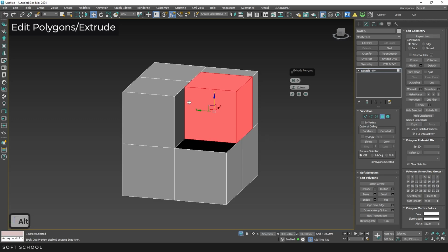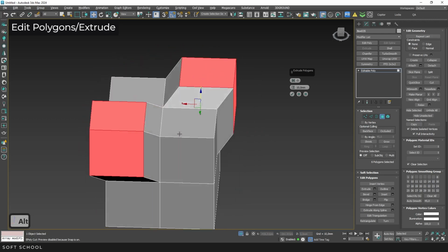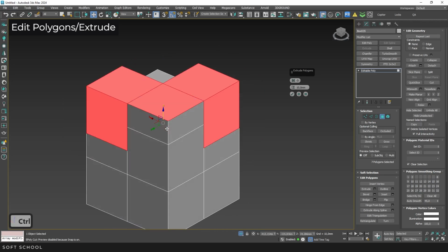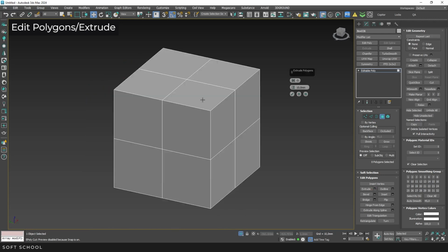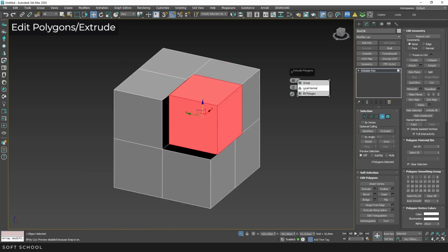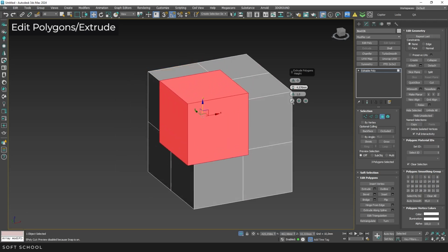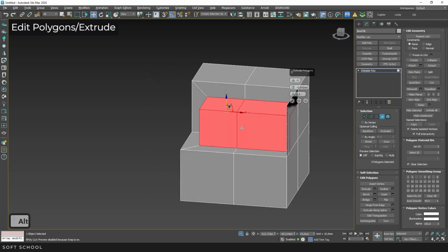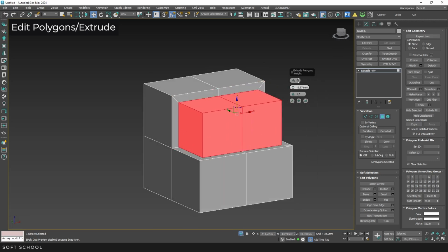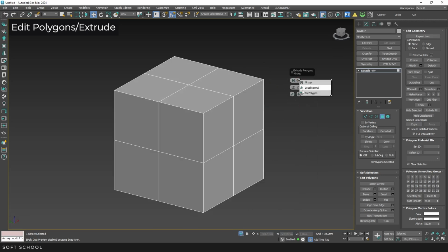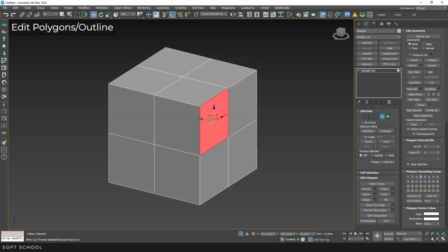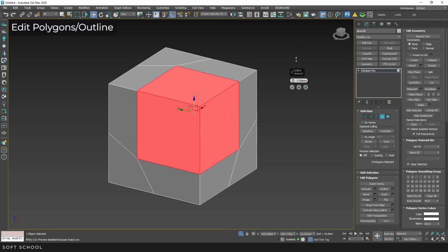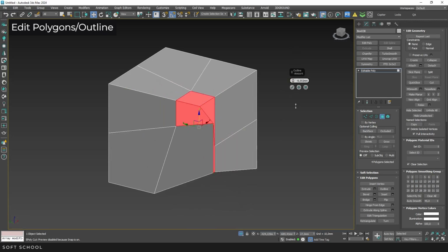If a non-adjacent group of polygons is selected, it will have its own extrusion vector. Further, polygon selection will make them one group. The second mode works along each polygon's normal, where adjacency matters. The third mode extrudes each polygon separately, regardless of selection. The next tool, Outline, reduces the outer edge of each adjacent polygon group, working well on symmetrical polygons.